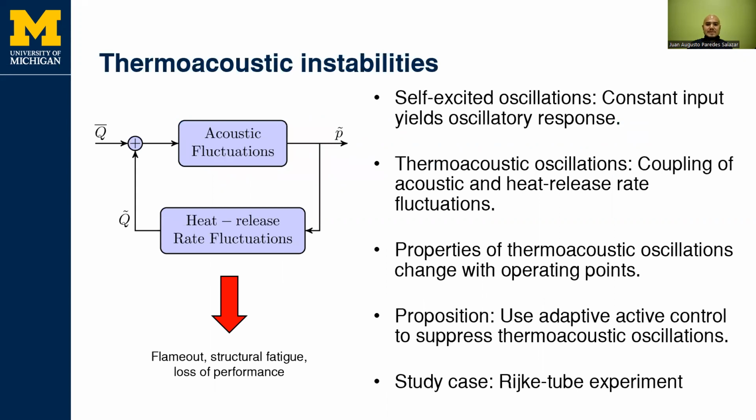Self-excited systems are systems that yield an oscillatory response under constant input. The coupling between acoustic fluctuations and heat release rate fluctuations may give rise to thermoacoustic oscillations, which may cause flameout, structural fatigue, and loss of combustor performance. Although some systems are designed to minimize these effects within a range of operation, changes in operating point and field property variations may still cause thermoacoustic oscillations and flameout.